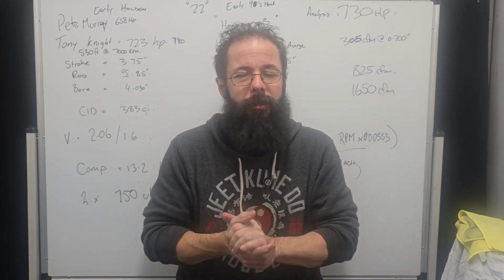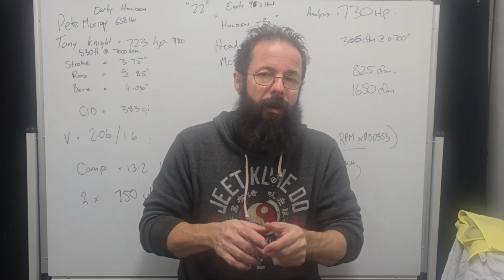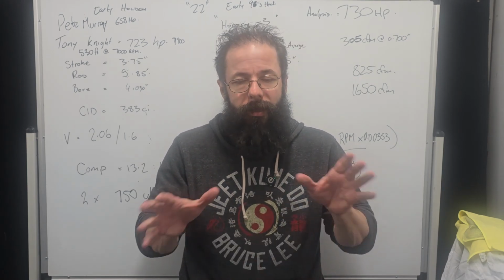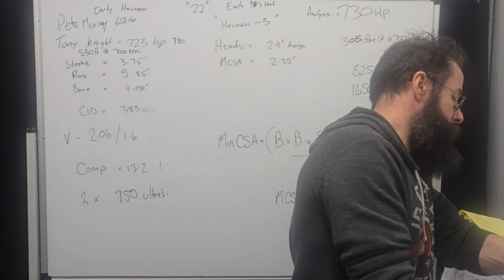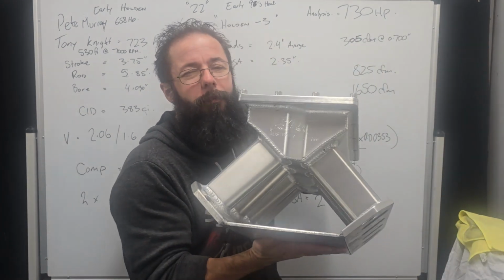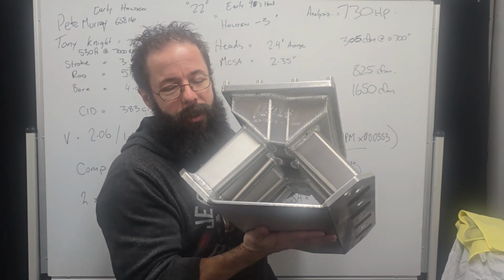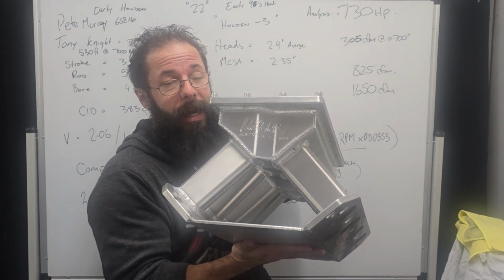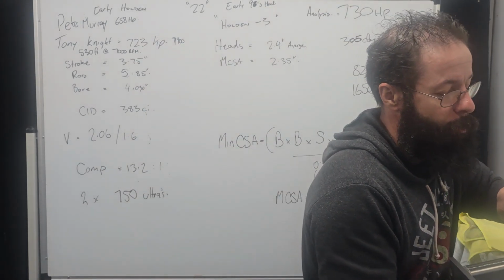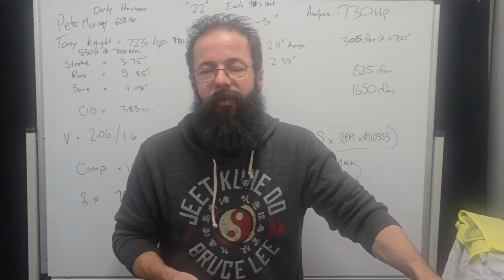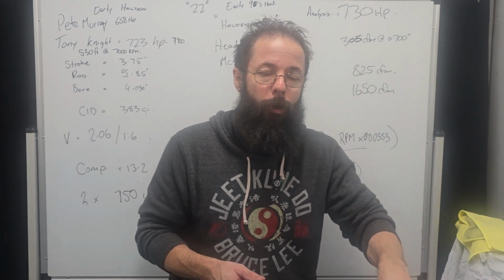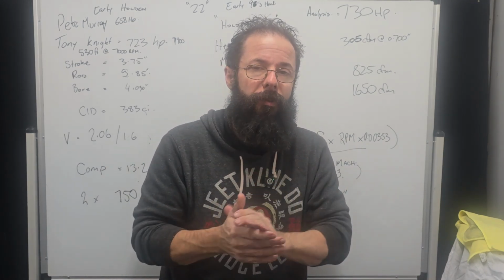So we just last year did 427 and a 454. Custom intakes and stuff like that as well. And just a quick example, this is sort of what the manifolds look like on the Holdens. As you can see, really wide belly, which allows us to... this is one I've designed for a VN. That is slightly high port, but as you can see, the port is off the floor.